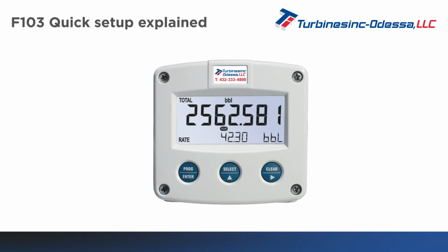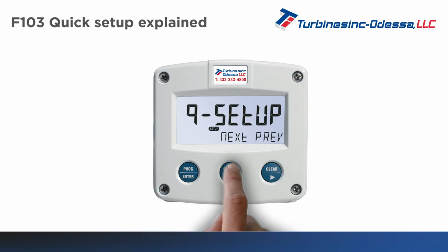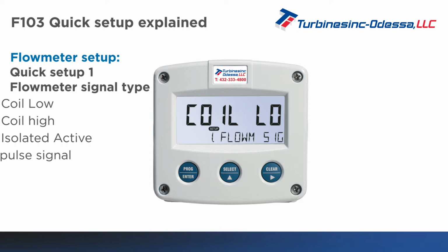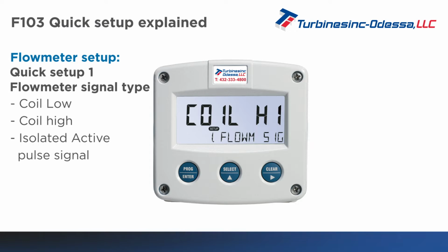Let's take a look at how this works. To enter the quick setup, simply press the Program button once. A welcome screen is shown. From this point on, you can navigate to the next menu item by pressing Select. You can use the Clear and Select buttons to navigate through the menu. Flowmeter setup. Quick Setup 1. Here you can set the flowmeter signal type, coil low, coil high, or isolated active pulse signal.